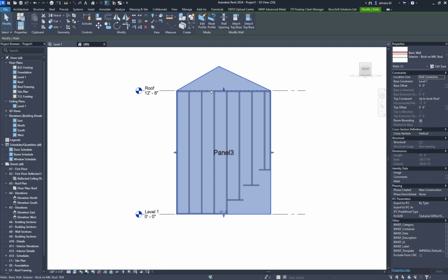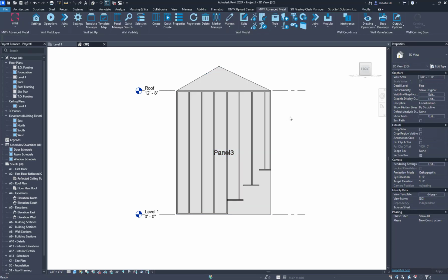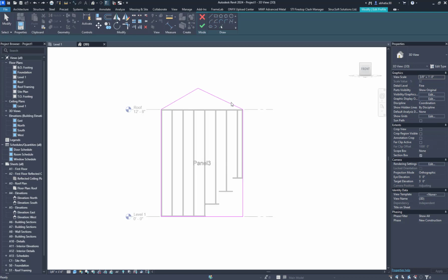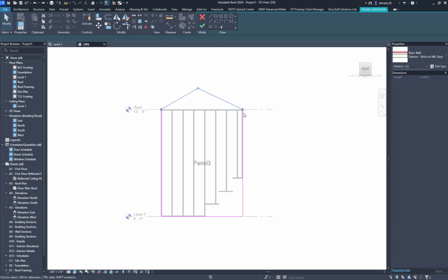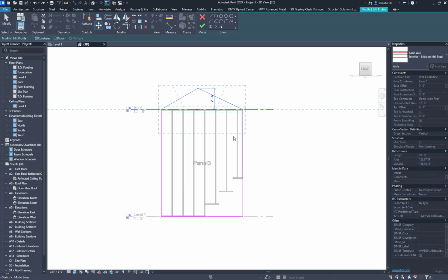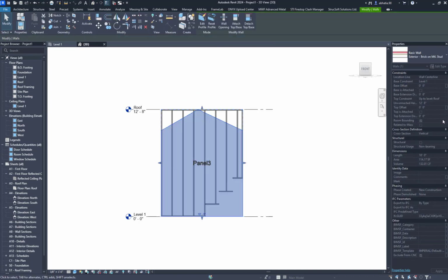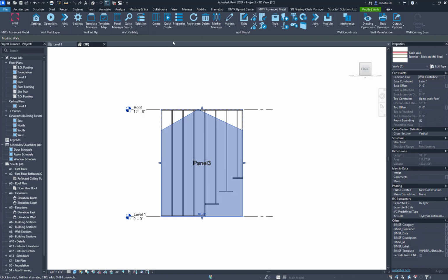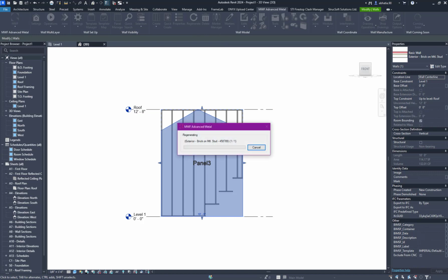And the reason for that is our reference plane, our top constraint reference, is actually stopping here. Okay. Whereas if I was to have done the slope by placing it inside the reference, so if I go ahead and move that and have that be right there, this is now true for our unconnected height to be 12 foot 8 because the top tip of that vaulted ceiling is at 12 foot 8. Okay, so if you're ever trying to use that value to grab height data, just be mindful that this is something you have to consider as well.